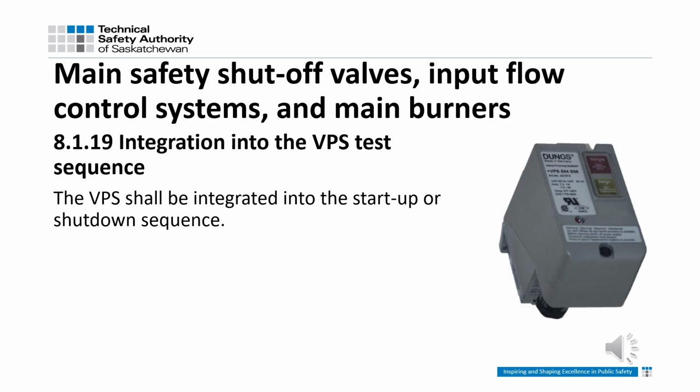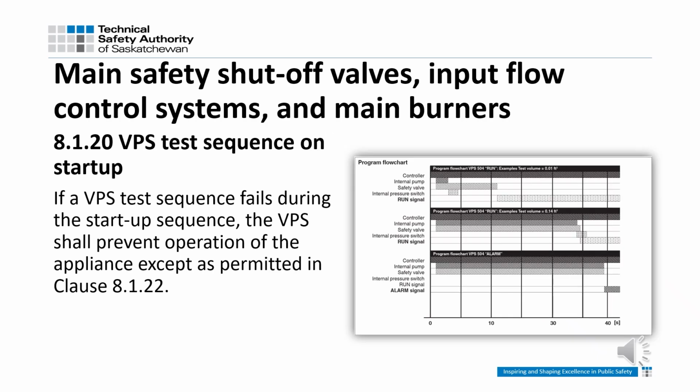8.1.19 Integration into the VPS test sequence. The VPS shall be integrated into the startup or shutdown sequence. 8.1.20 is the same requirement in 2025 as 8.1.17 in the 2020 code, which requires the VPS to prevent burner ignition if the test sequence fails during startup.